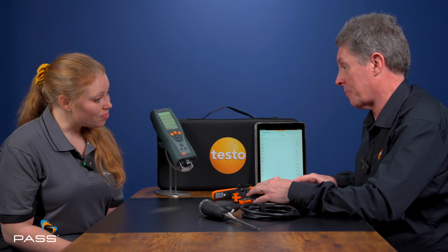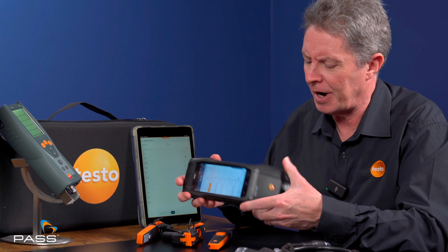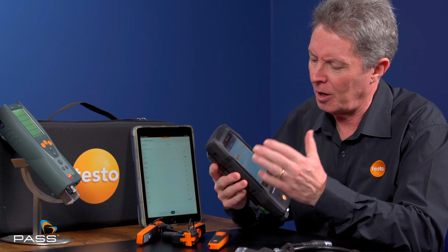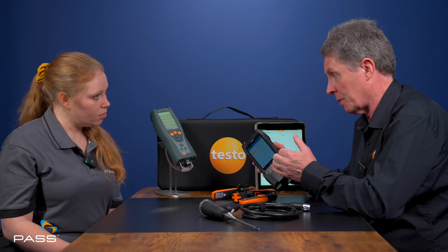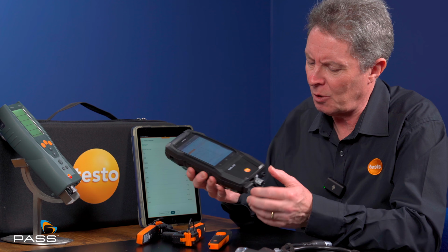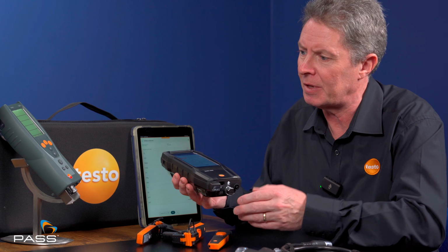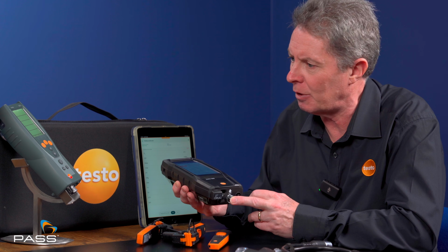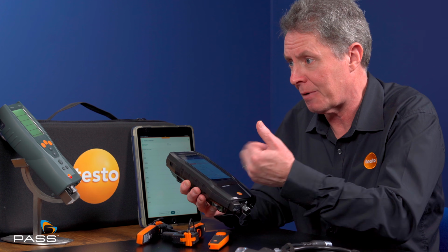Okay, I think we're very proud of our German heritage. We're all about the build quality. If you look at the design, powerful magnets, easy to drain down condensate trap, lithium-ion batteries in both devices, and a smart screen as well on the 300. But sometimes it's some of the little overlooked details. For example, one of the really critical bits of any Flue Gas Analyser is your sample that you're bringing down from the sample point to the instrument, making sure that whole pathway is gas tight at all times. Because if it's not, you're going to be introducing excess air. It's going to make your readings incorrect.